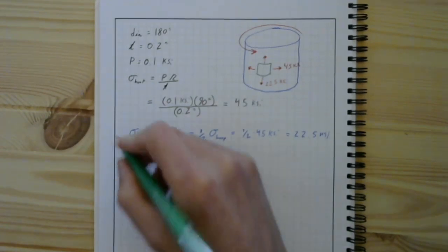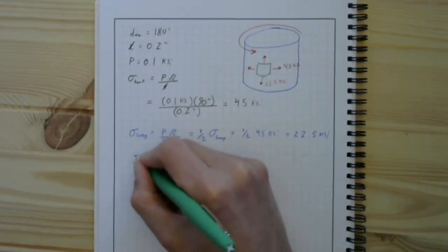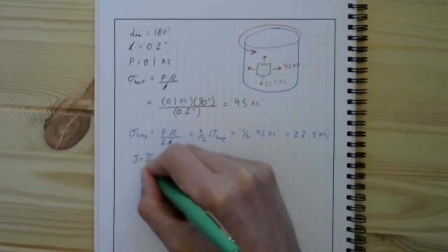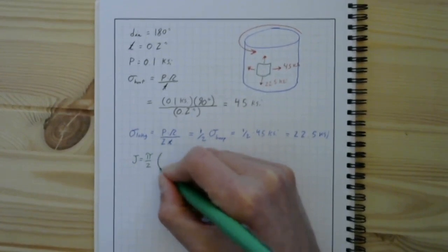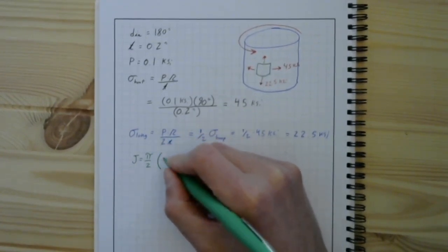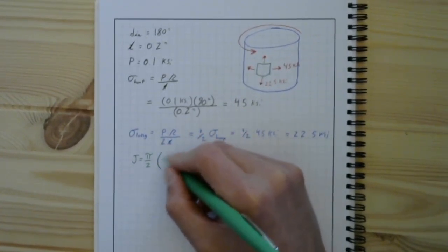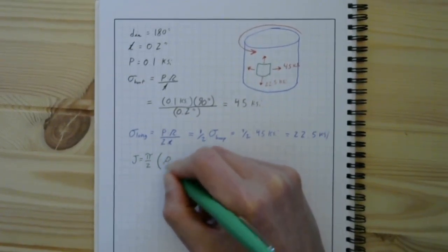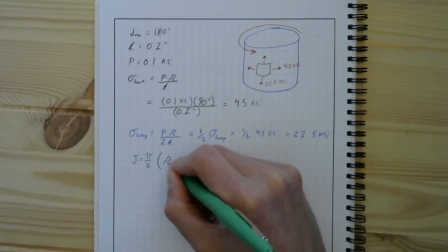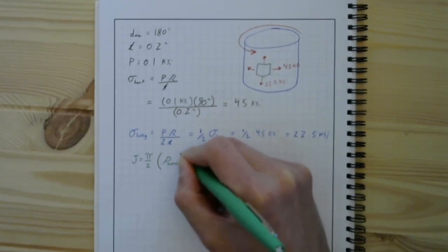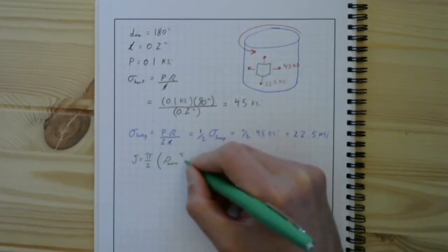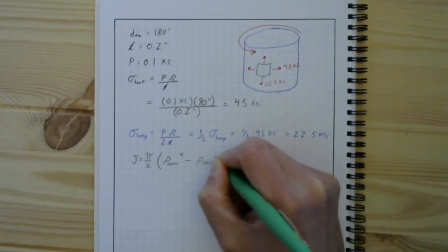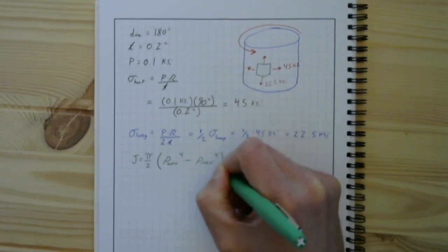Now, our equation for our polar moment of inertia, J, is, of course, pi over 2 times the outer radius, which I guess we're calling rho usually, to the 4th minus the inner radius also to the 4th,